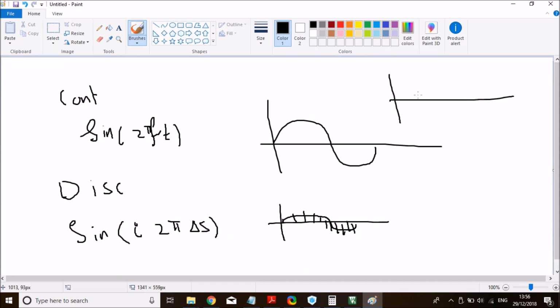It will create 50 samples. It will take 50 samples to make one sine period. And because I set my sampling frequency to 50 kilohertz, that will ensure we get 1 kilohertz at the output, because this got divided into 50 samples. Just pause the video here if you think you didn't get it.